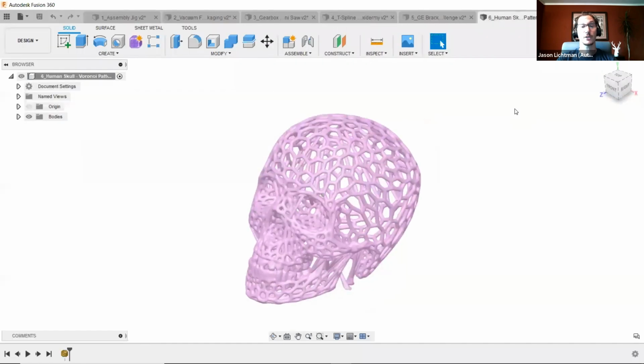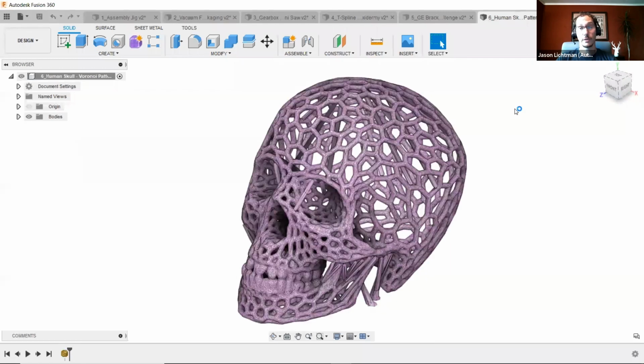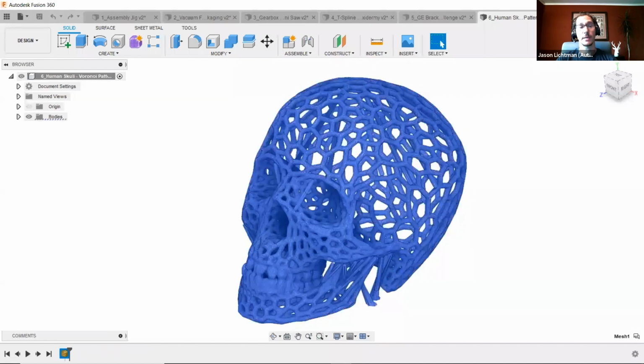Here I have a mesh that I downloaded. This mesh could come from your own design. It could also come from a website like Thingiverse. But if you take a design like this and import it into Fusion, you might need to edit the mesh itself. Well, you're going to be able to do that. We have what I would call light mesh editing inside of Fusion 360. Here I have my mesh editing feature at the very bottom of my timeline.